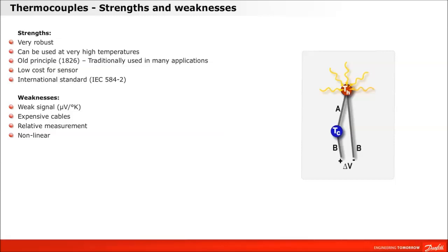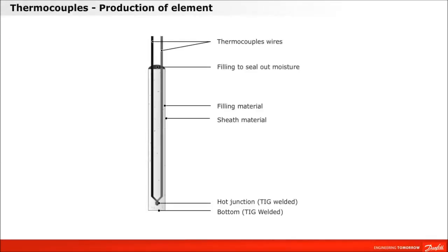The thermoelectric voltage created is a small microvolt per degree signal. The measurement is a non-linear relative measurement, and special compensation cables have to be used to ensure a proper temperature reading. When working with thermocouples, moisture is enemy number one.